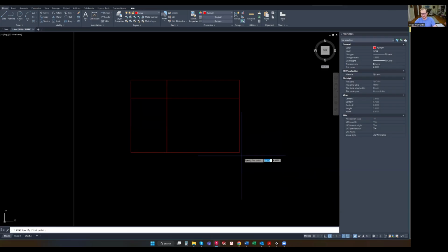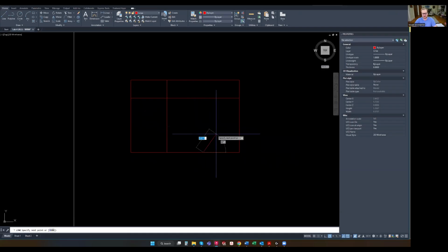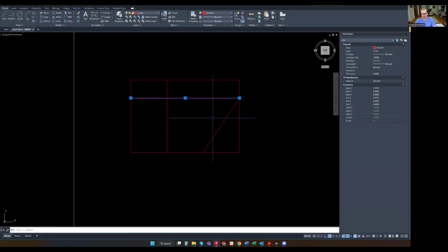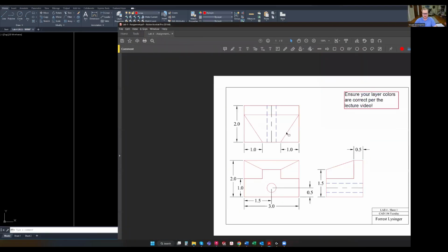So let's go ahead and do that towards the left. So I'm going to hover, drag out this way, bring my mouse out this way, 1 enter. And now we see we have our line starting 1 inch from this point to the left. And instead of drawing a line straight up, we could just draw a line to our 1/2 inch offset from the top, just like that. And if we bring in our drawing here, we can see what we just created is this line right here.